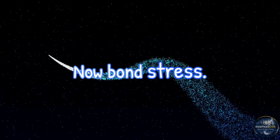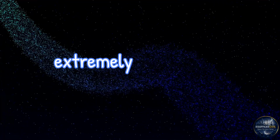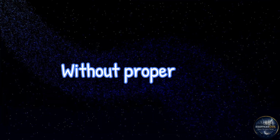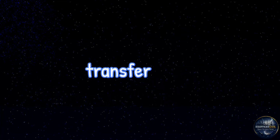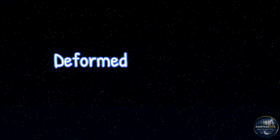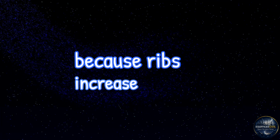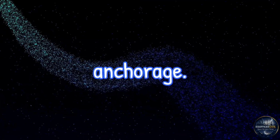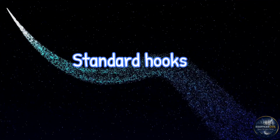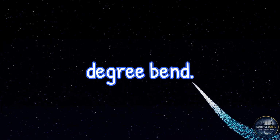Now bond stress. Bond between steel and concrete is extremely important. Without proper bond, steel slips inside concrete and load transfer fails. Deformed bars improve bond strength because ribs increase friction. Hooks and bends also improve anchorage. Standard hooks generally use 180-degree bend.